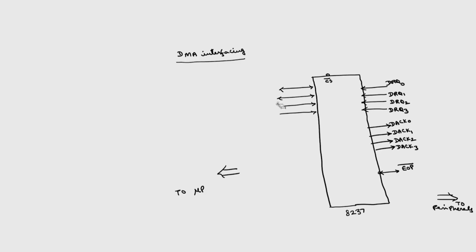Or this unidirectional. This is A0, A1, A2, A3. Then we have a 3 to 8 decoder, 74LS138. This I have discussed in the memory interfacing also. This is a 3 to 8 decoder, 3 inputs, then 8 outputs, O0 bar, active low signals all.